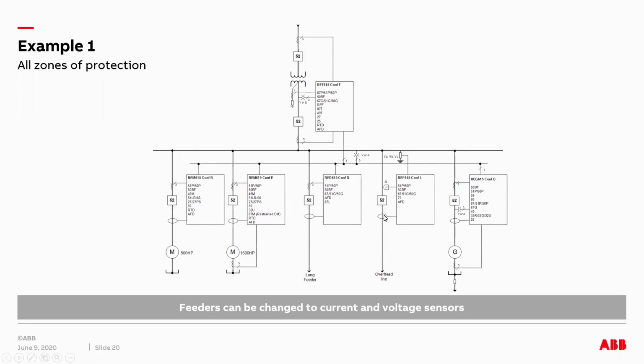For ground fault application, we would still need a ground CT, because, as you see, the ground CT or the donut CT is encompassing all the three phases. So there is no sensor technology for a ground or equivalent to a donut CT at the moment. So if there is a requirement to measure the ground current directly, we need to use a donut CT.